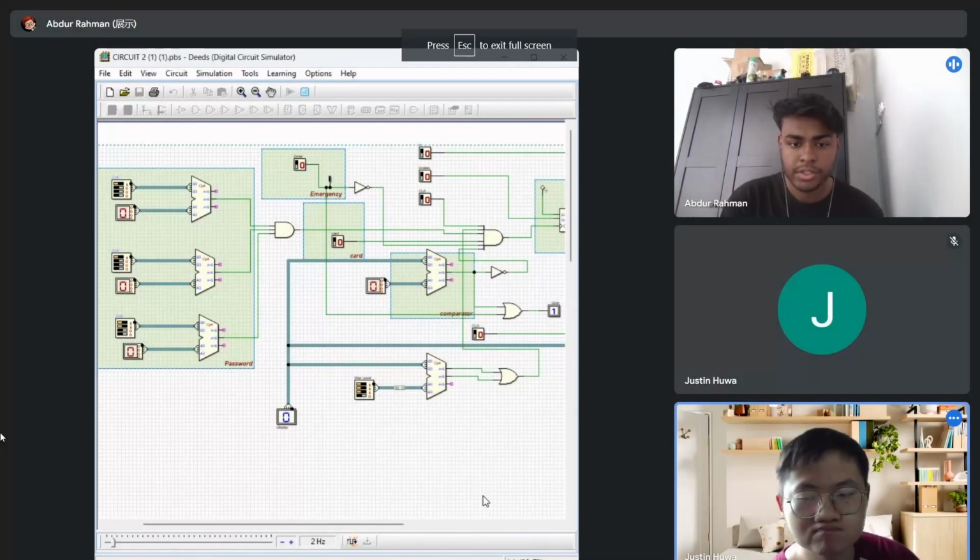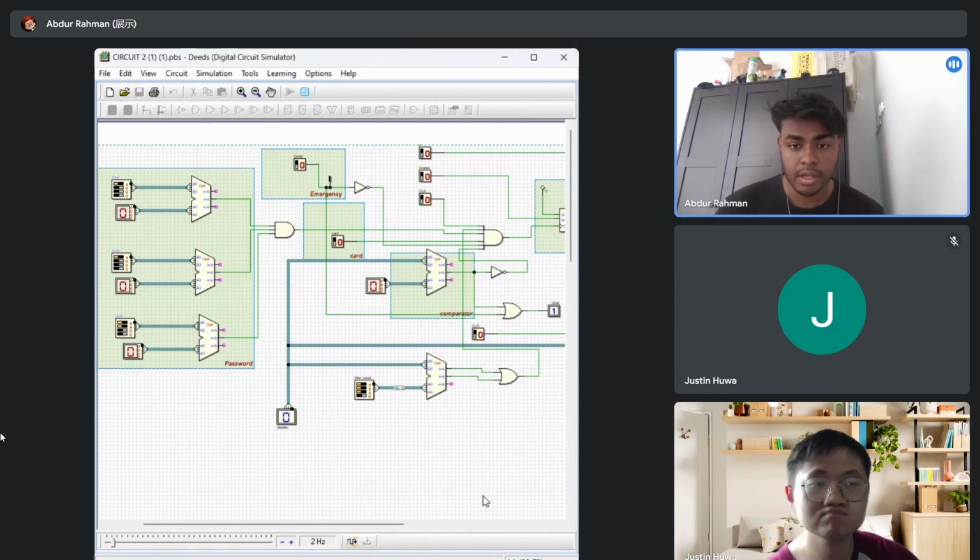All right. For the advanced circuit, to enhance the functionality of our lift control, several advanced features were introduced. Firstly, an automatic door system was implemented, which opens the door when the desired floor is reached, facilitated by a door switch, additional input switch for a card access and emergency switch also implemented. This DIP was implemented for the passcode. Three DIP switches were configured.